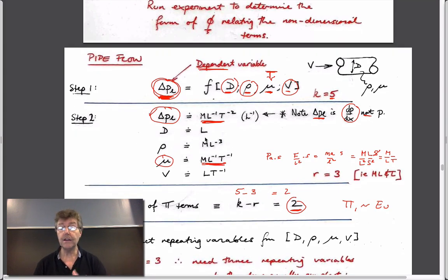And so really what we've done is we've really just defined what we think the physical processes are that affect our system. We have fluid flowing. The drag on the side is due to viscosity. Therefore, viscosity might be important. You could make the case that density might not be important because it's all being driven by pressure. But certainly changes in velocity along a pipe would be driven by energy in the system. And to accelerate a fluid, you have to act against its density to be able to change its momentum.